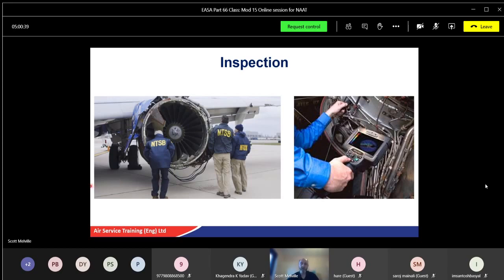The gas turbine itself is simple construction, and it tends to last a lot longer compared to a piston engine. Some engines are now overhauled on condition only, they're that good. But usually you've got things like turbines which have a life component. Good maintenance means keeping an accurate record of all the engine operating parameters: thrust, vibration, oil, etc. Any wear and tear, degradation of the health of the engine, gets recorded, and that can help improve the engine through later years as well.